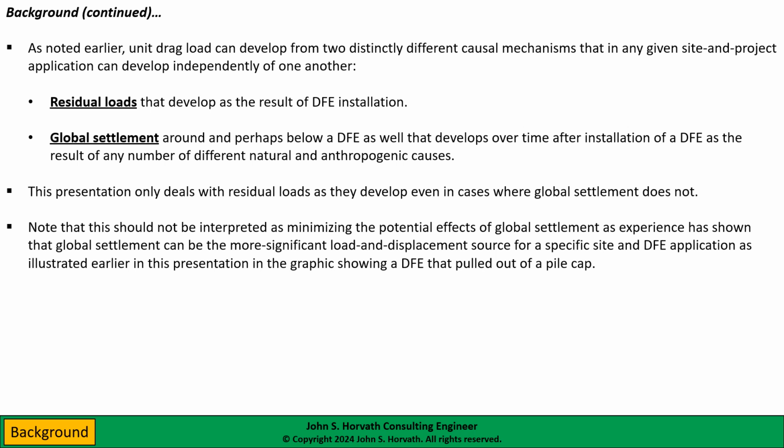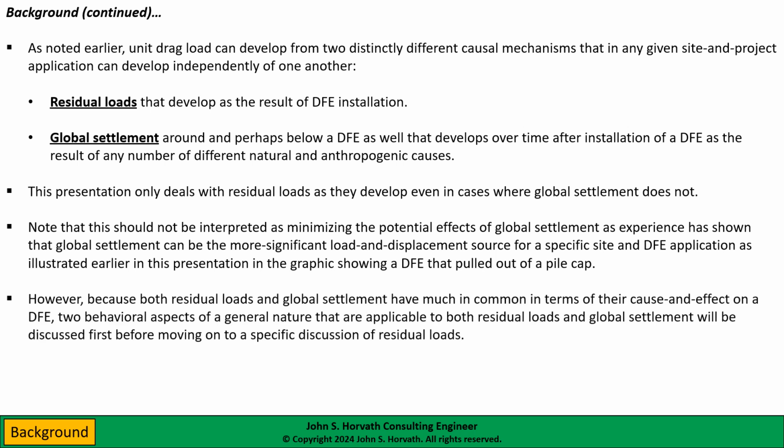Now note, I don't want to minimize the potential importance of global settlement, as experience has shown that it can be the more significant load and displacement source at a specific site and DFE application, as I showed you a few slides ago in the case of a pile that was literally pulled out of the pile cap. Certainly ground settlement was the predominant mechanism of concern there.